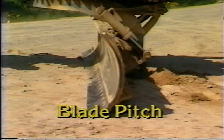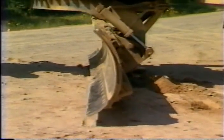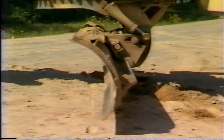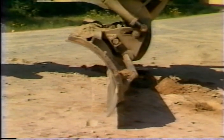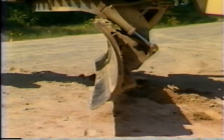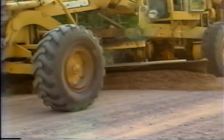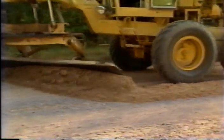The next movement is blade pitch. Blade pitch refers to the vertical angle of the blade. The blade can be tilted forward, backward, or remain in an upright position. A forward angle of the blade creates a dragging action on the road. The blade does not cut into the roadway surface.